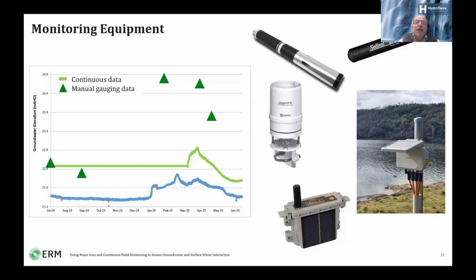People pull the logger out to manually download it, and they lower it back down, and people used to hang them on chains or wires, and sometimes it'll be hooked around the eyelet in the well 2 centimeters higher than it was before, and suddenly you've got this beautiful time series data that's 2 centimeters higher than it used to be, and that just doesn't happen. So it's really good to be able to check those things. Doing those spot measurements allows you to adjust those readings when you do find the error.